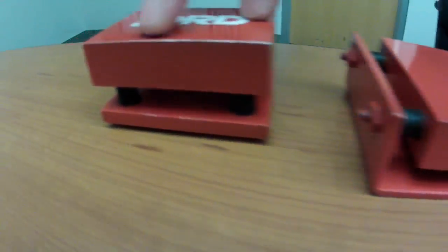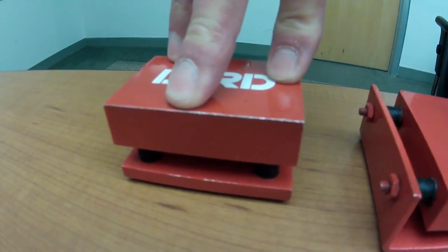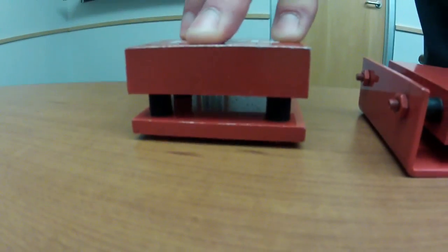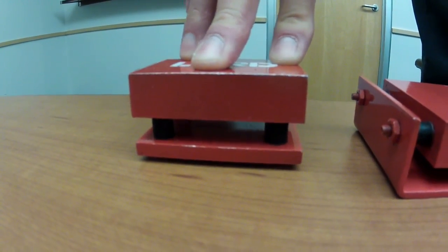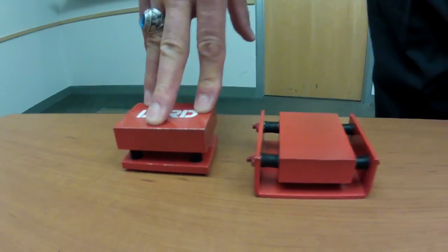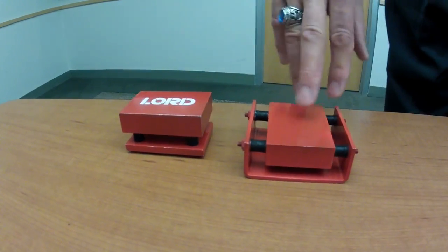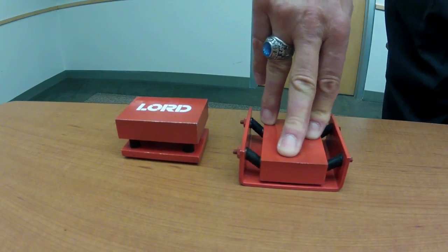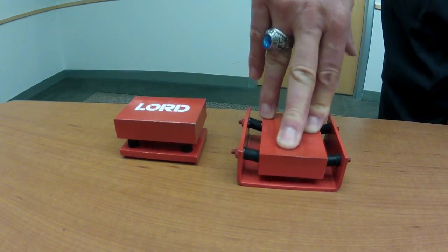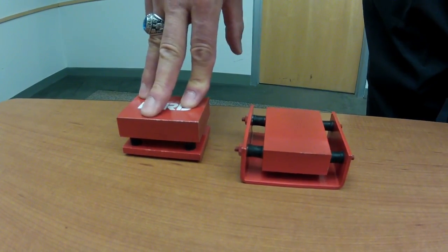The same isolators can also be installed vertically, which gives different deflection characteristics and a different natural frequency. So that's why it's critical and important that you tell us which way your isolators are mounted in your application, because we can have different performance in shear versus compression, especially with sandwich mounts.